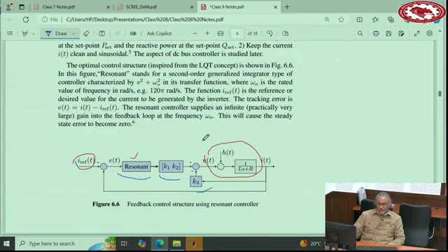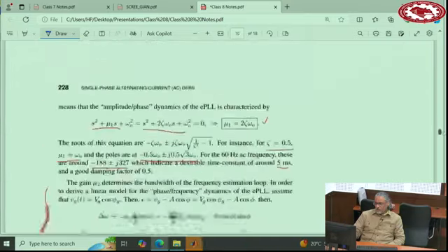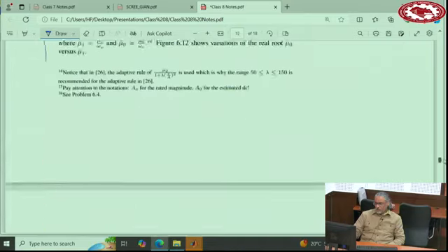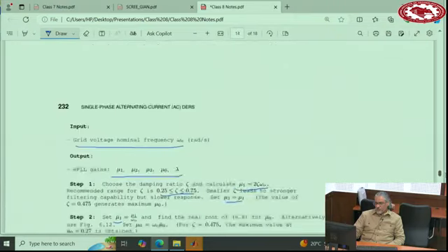We used PLL for the feed-forward term here and also for the reference current. So we discussed the PLL in detail. We discussed how to limit the current also. Next and the last step would be to design K1, K2, and K3, the controller design, which by now should not be difficult for you to do. Just writing down the equations.